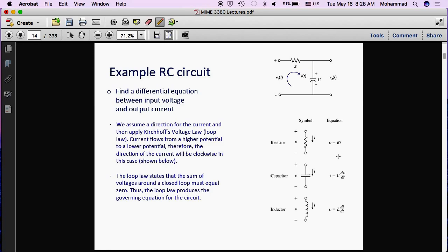Now, in other words, is an ideal resistor a dynamic system? Do you remember the definition of dynamic systems? What was the definition of a dynamic system? Absolutely. So if you consider a resistor as a system with its input as the voltage and its output as a current, you can imagine that, right? You attach a battery and you measure how much current passes through it. You just put a multimeter in series in the circuit, and you measure the current passing through.